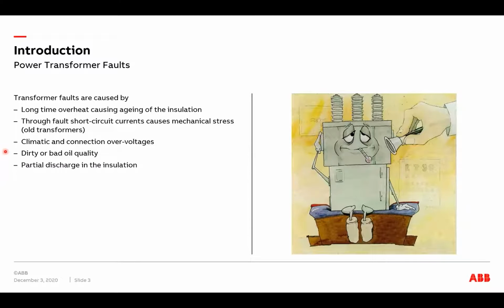The insulation level of the oil reduces due to contamination, which can be the result from, for example, overload situations where winding temperature gets high, or in case of partial discharge in the winding insulation. As the oil insulation level reduces, there will be a higher risk of flashovers, for example, during overvoltages.